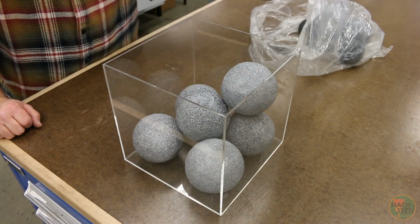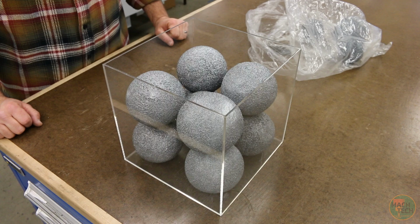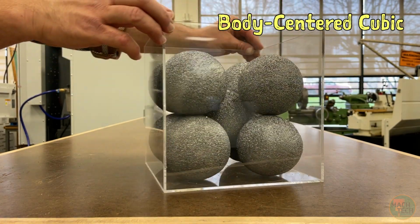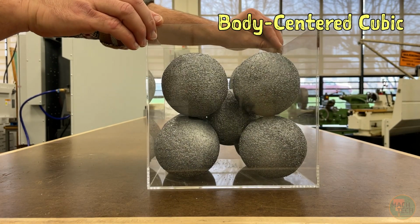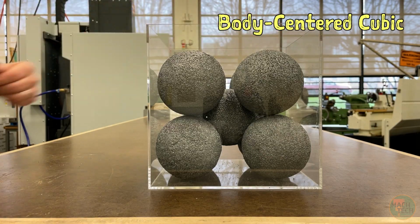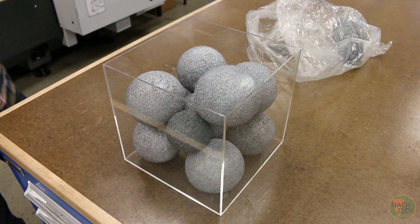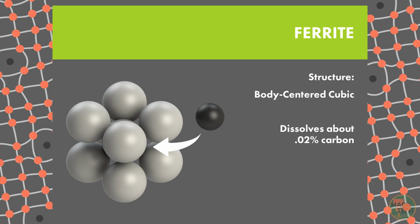Okay, I'll add another layer. Again, the third layer is a mirror of the first, with 4 atoms, 1 in each corner. This structure is called body-centered cubic, because it's shaped like a cube, with 1 extra atom in the center of the cube, or the body. Since the way the iron atoms pack together is slightly different in the body-centered cubic structure, there are fewer spaces for carbon atoms to smush between them, and perhaps you can see that even a single carbon atom distorts the lattice structure dramatically. Ferrite can only dissolve about 0.02% carbon.